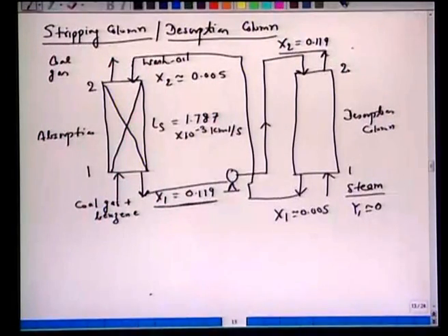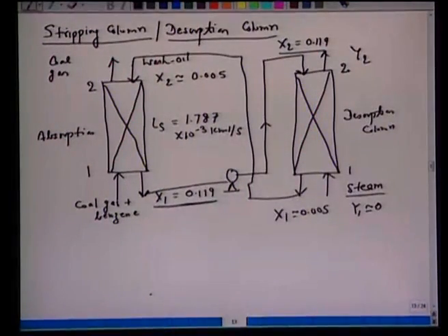So try to understand what we want to achieve in this desorption column. Typically in industries we have this flue gas, which here was coal gas containing benzene, and we were asked to clean this coal gas. To do this we had wash oil as a solvent, but the solvent is quite expensive. When this wash oil is used countercurrently to remove benzene from this flue gas, the spent liquor contains a very large amount of benzene. Now this spent liquor has to be cleaned again by a different solvent and fed back to the absorption column, because the solvent is quite expensive.